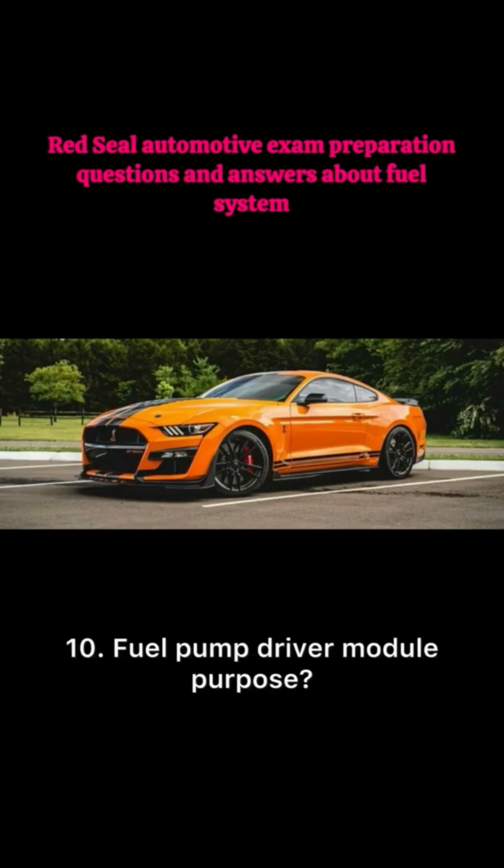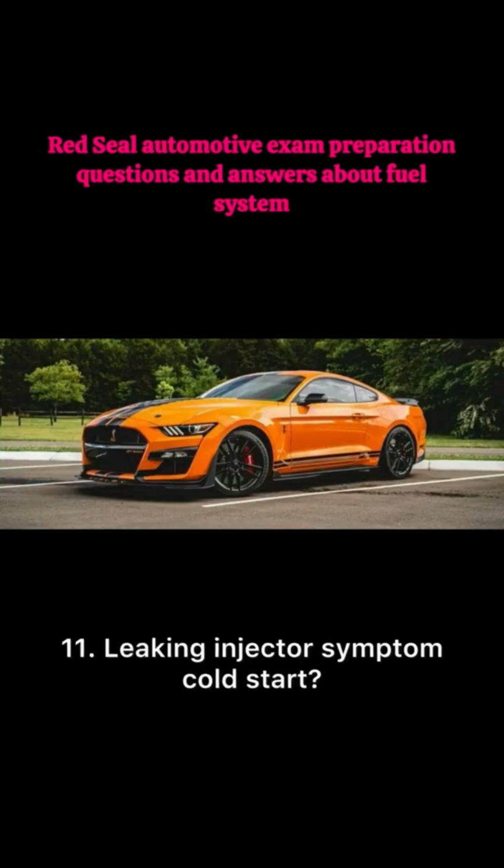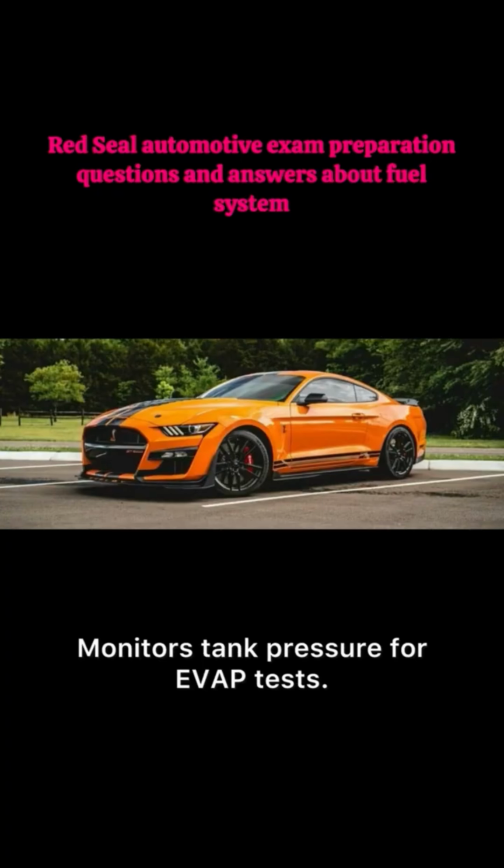10. Fuel pump driver module purpose. Controls pump speed on returnless systems. 11. Leaking injector symptom cold start. Hard start, black smoke, fuel smell. 12. Fuel tank pressure sensor job. Monitors tank pressure for EVAP tests.